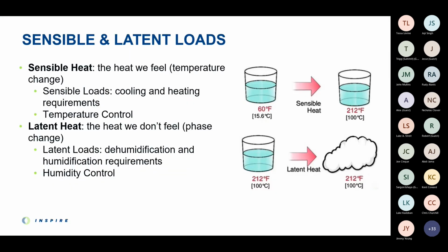So sensible and latent loads are how we are going to quantify these dynamic needs of an indoor plant environment and appropriately size an HVAC system for a given room. Inaccurate load calculations lead to undersized or oversized equipment, which both present challenges. For most HVAC applications like offices, residential homes, or even gymnasiums, there are published standards from industry organizations that engineers can refer to for guidance when calculating loads.